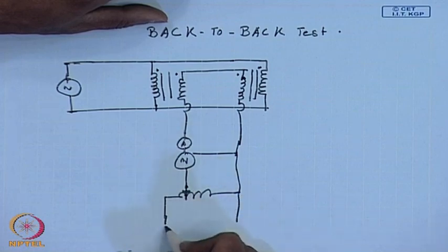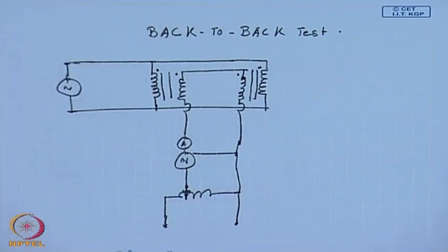A similar arrangement has to be done for a 3-phase transformer now. So, let us say we have a 3-phase transformer. If any particular side is star connected, what we should do? We have to connect those star windings in series, while the other side has to be connected in parallel. So, the following figure shows an arrangement.